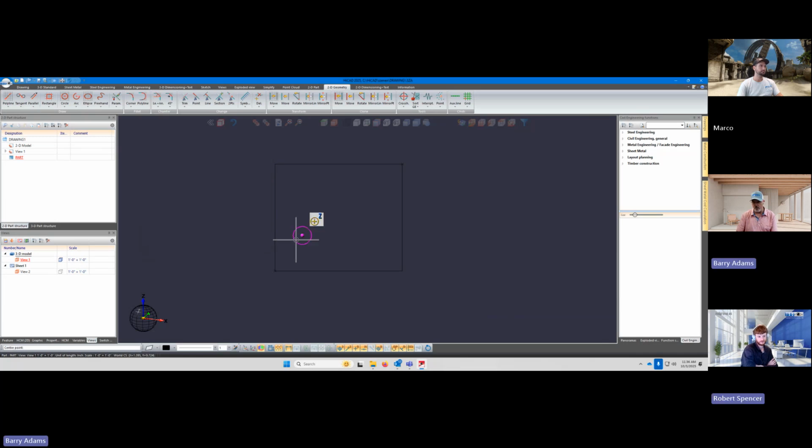Now there's our 1/4 inch circle. Now, one thing, the command is still active. You see how at the bottom left corner it says next center point? That allows you to go right away to the next circle if you want to. You can also close the command by hitting the middle mouse or escape here.